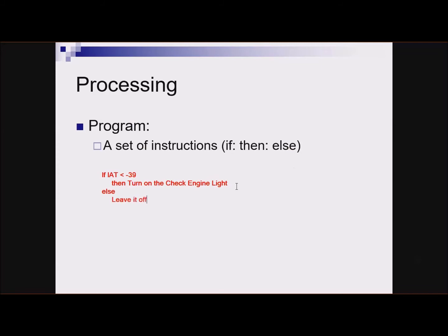And there can be multiple things, right? So it could say instead, do it again. We know from the lab that, when we pulled the electrical connector off that intake air temperature sensor on some of the vehicles, and on a lot of vehicles this happens, we're looking at the scan tool, it reads negative 40. When we shorted the wires together, it read like 248 degrees. Neither of those obviously would be a normal intake air temperature reading. So the logic for determining whether to turn the light on in the computer might look more like this, right?